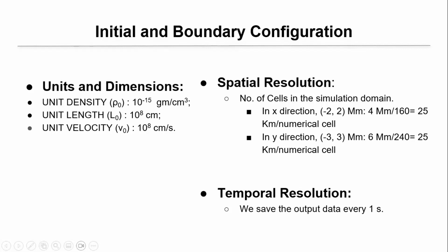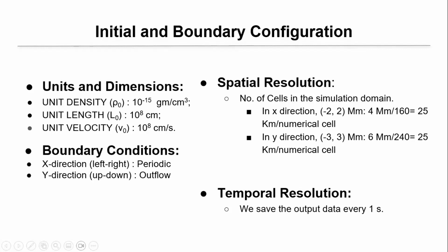In temporal resolution, we get the output data at an interval of 1 second. In the case of the boundary condition, we have put the X direction as periodic, from left to right, and in the Y direction, from top to bottom, it will be outflow.